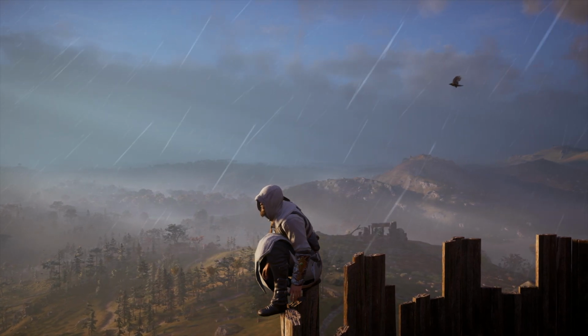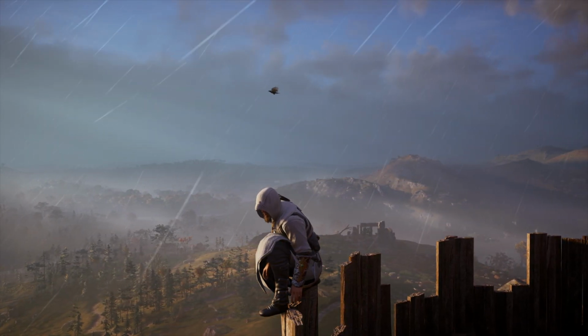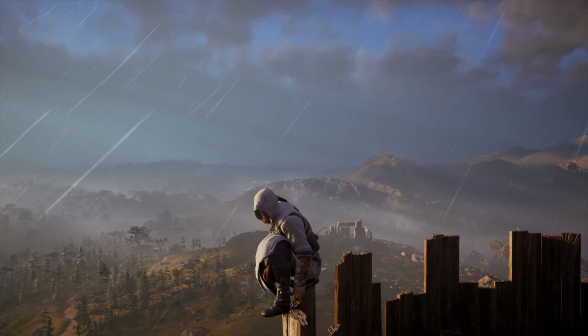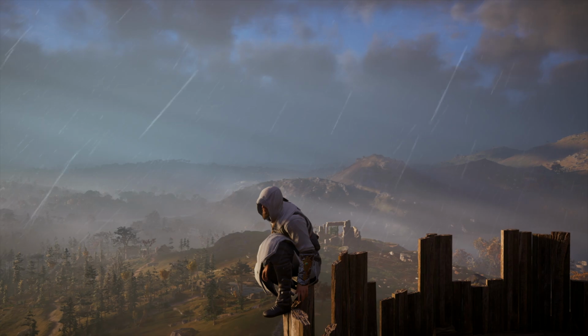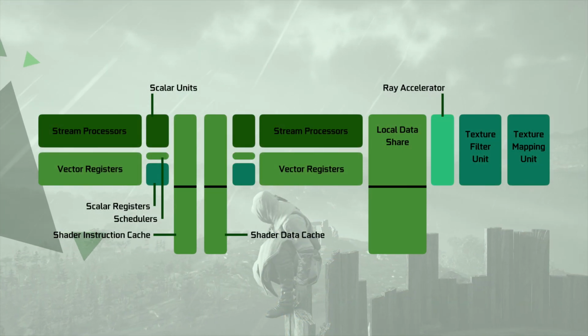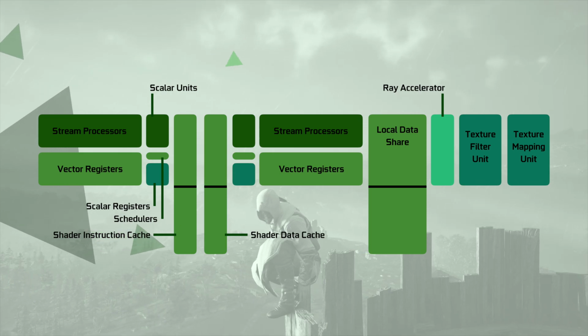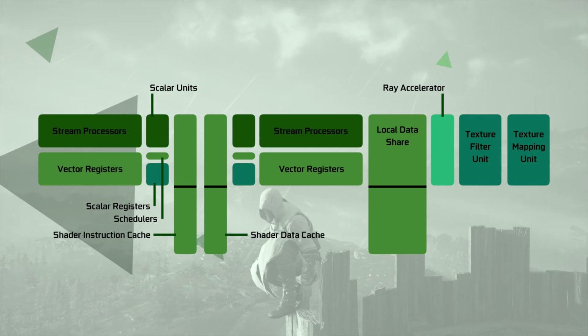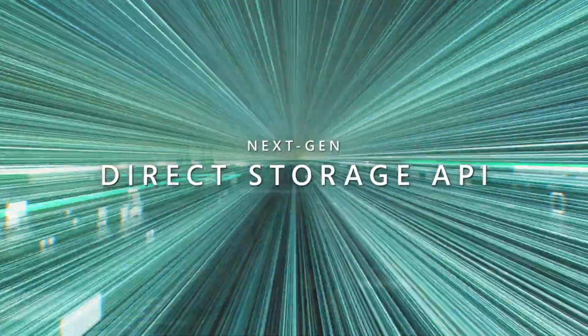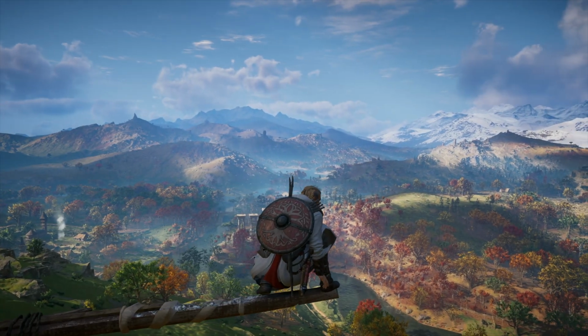Speaking of technologies that are supported by RDNA 2, the major improvement is real-time ray tracing hardware acceleration support that makes the ray tracing calculations 10 times faster. Each RDNA 2 CU has one ray accelerator unit for that purpose. Furthermore, there is hardware support for variable rate shading technology, which lets the GPU output the image with different resolutions on different parts of the screen. Along with RT and VRS, there's also mesh shader support and DirectStorage, which we already overviewed in the Xbox Series S technical analysis.